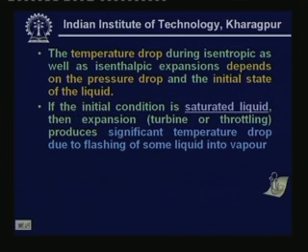If the initial condition is saturated liquid, then expansion, whether using a turbine or a throttling device, produces significant temperature drop due to flashing of some liquid into vapor. Okay, so let me explain this one.